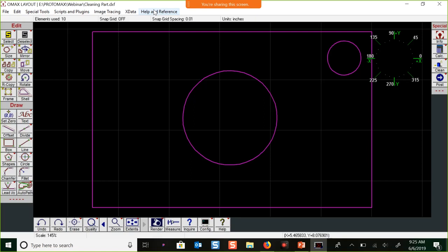I would probably put a sacrificial material in before you definitely started cutting to know exactly where you're at. But you could pretty much line it up relatively closely if you record your path start, and you put the part into the same equivalent position.